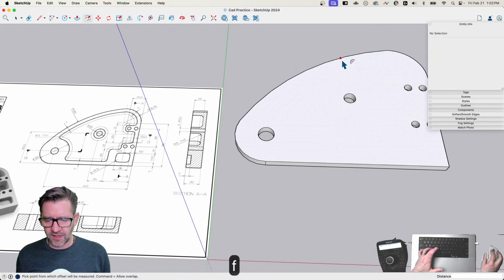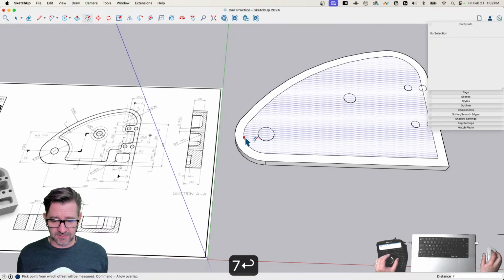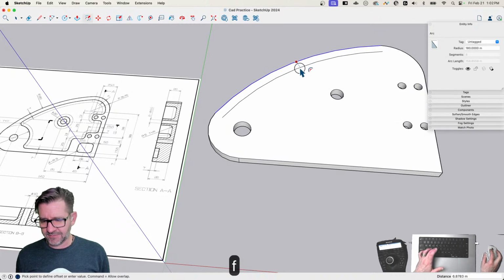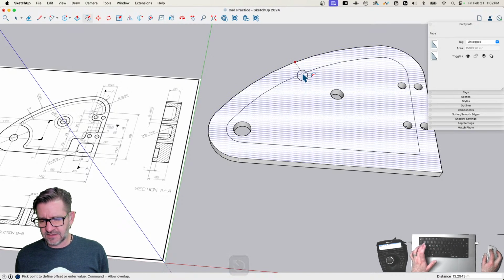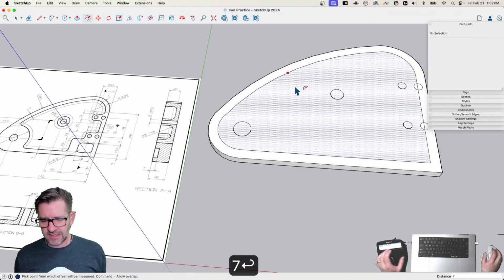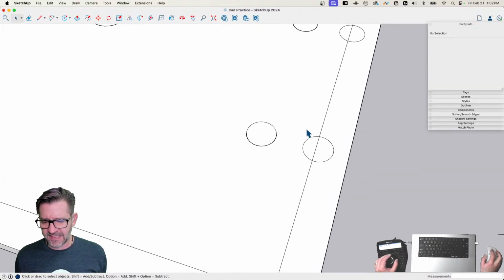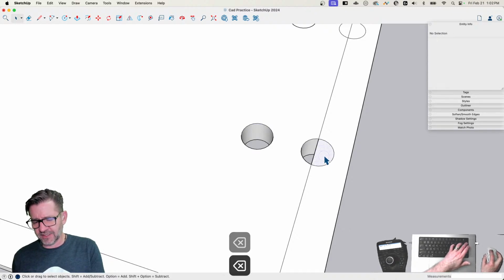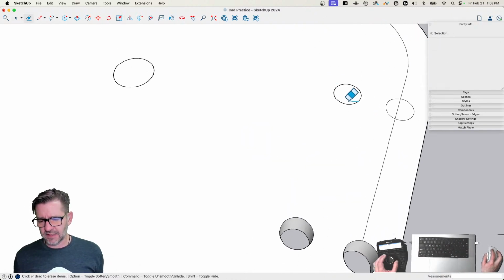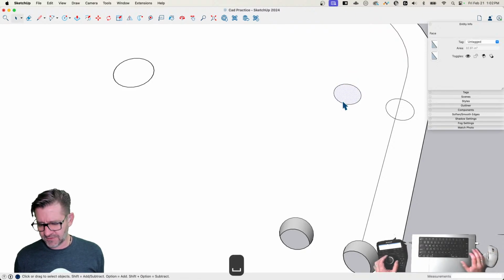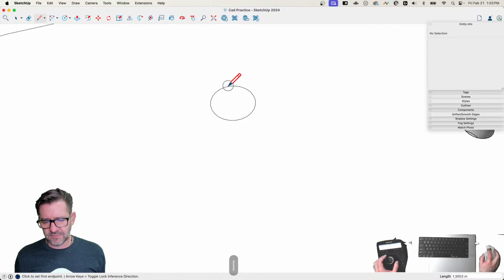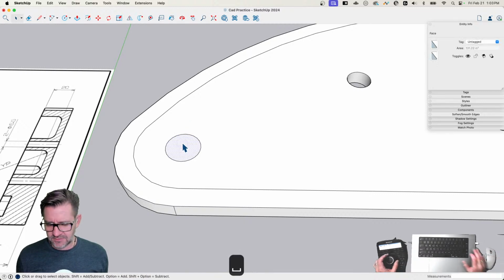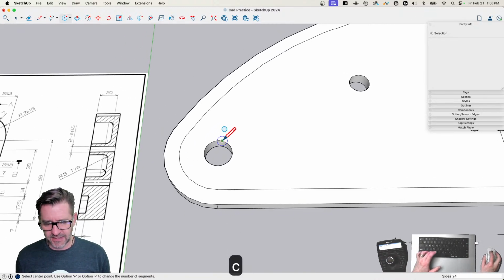All right, I'm going to do a quick offset here of 7, because I'm supposed to. Wait, what happened there? Here's what's happening: when I offset this 7, it puts it over the hole, so it recreates the face. So I end up with my holes covered up here. I might have to draw an edge on here to force that to recut through. Not a big deal. That actually argues for maybe doing some more of this in the original 2D layout, but anyhow.